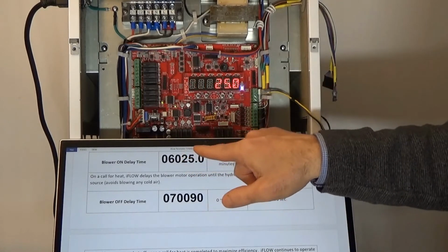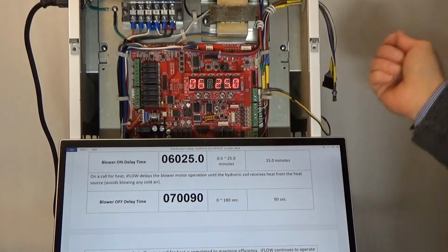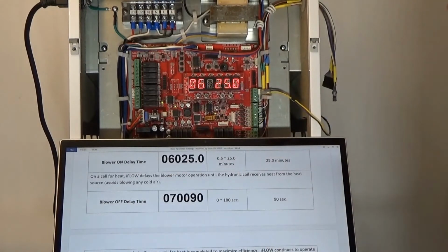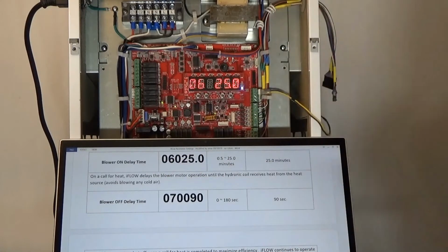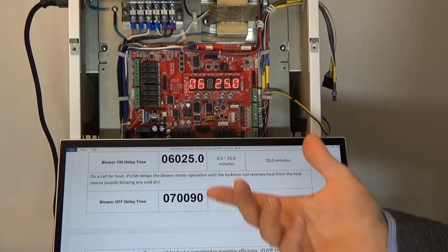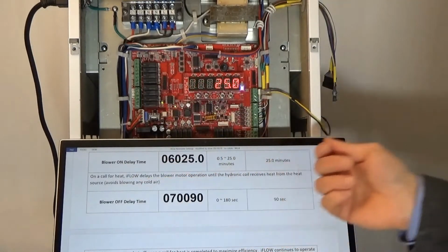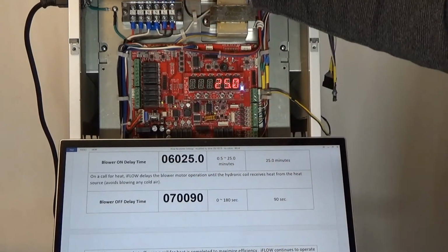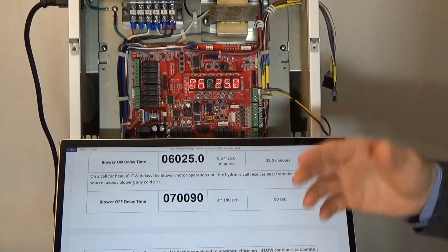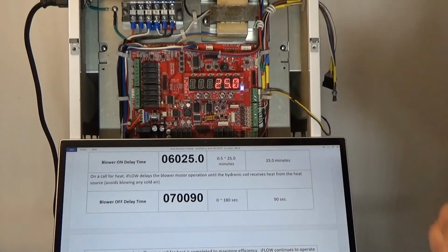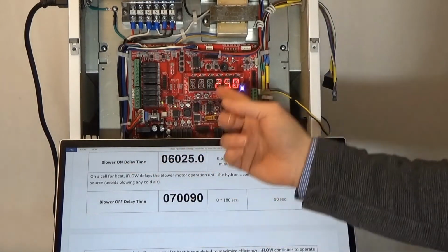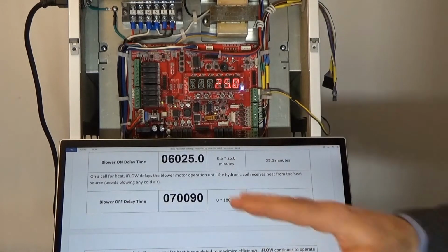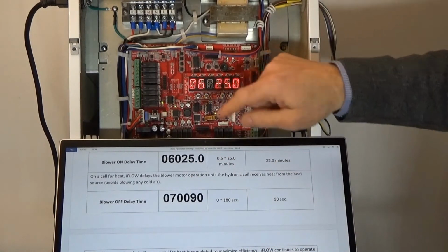But nonetheless, if you're in very close proximity to the tankless water heater, if that's your heat source, you could run this down to perhaps 30 seconds, 1 minute or 2 minutes, and that would normally be more than enough to get the hot water at temperature into the coil. But in the cases where you're running with a boiler or you have some domestic priority on your combi boiler, then it may take a little longer, and you can adjust that before we throw an error code. So that's what parameter number 6 is.